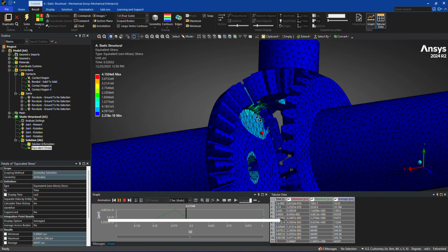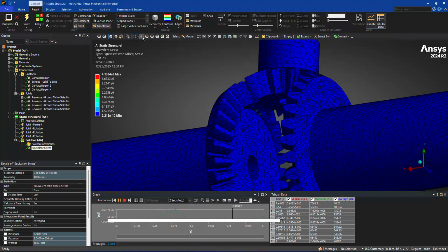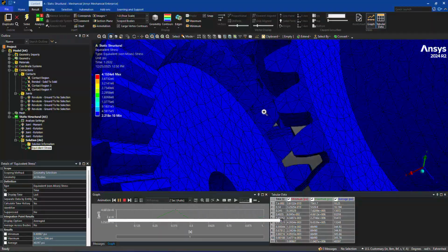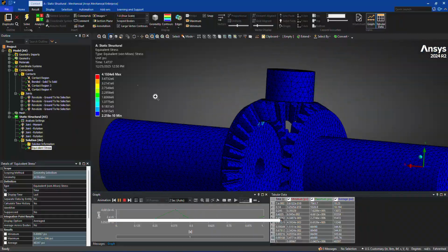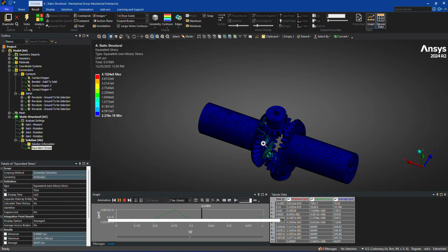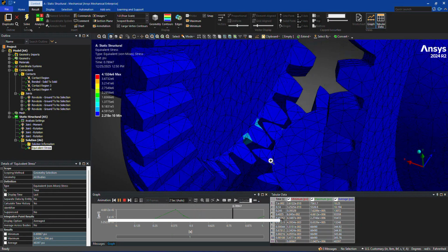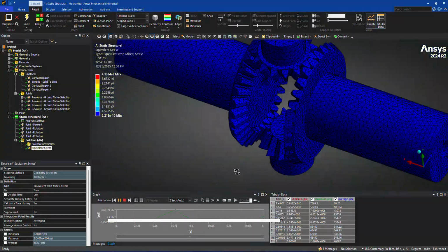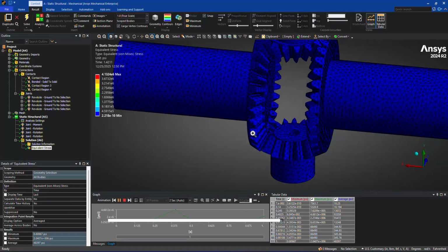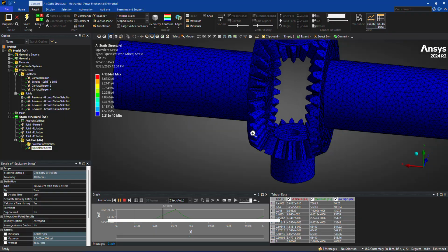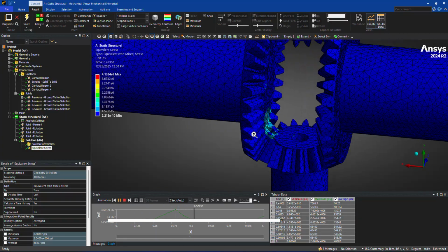See the rotation, see the stress here. So I have gotten a huge amount of stress here, almost 400 ksi, which is way too much. And I have also done the math for this condition, and the stress is not this much. So I guess it needs better meshing to get proper results, because this is a very complicated mesh.